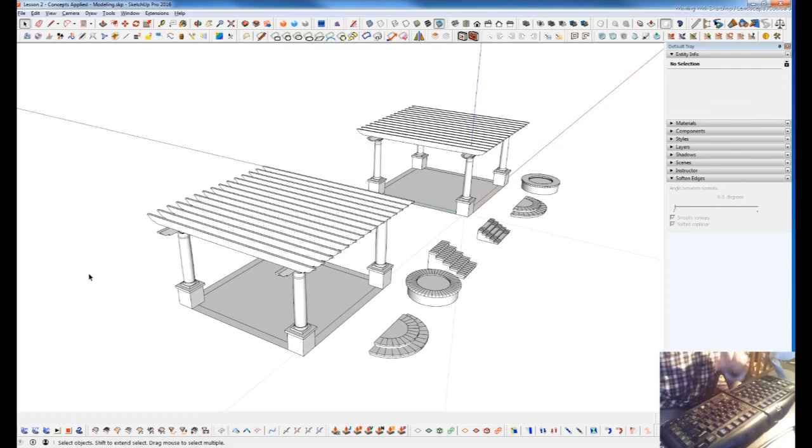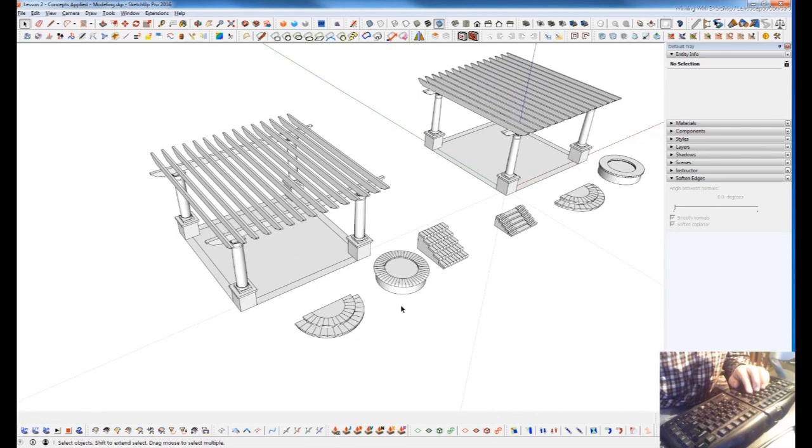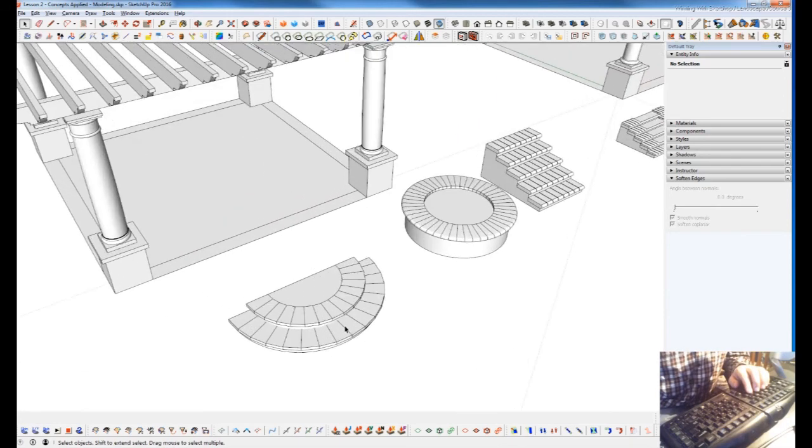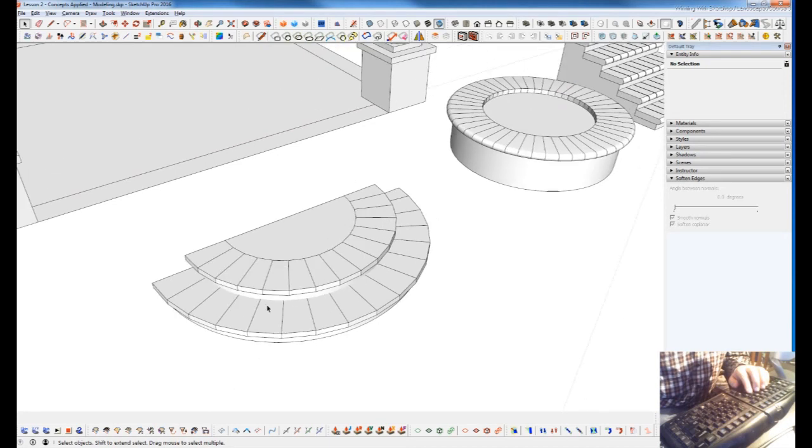And then I want to talk about something that is really important to understand, and that's the quad-based texturing workflow. That's going to help explain why we go through the process of creating proper joints, and why we do some of the things we do with creating all the caps, the step treads, any wall cap, fire pit cap, pool coping, anything that comes along a curve which is going to have a jointed material in it.